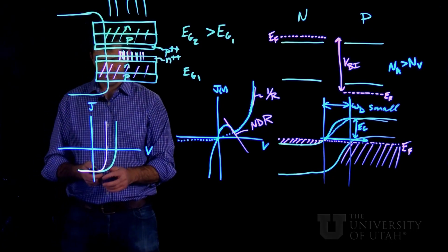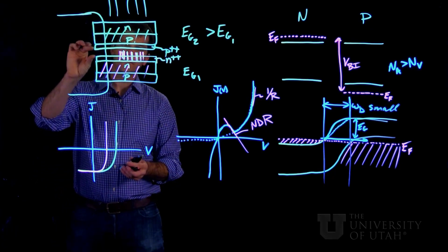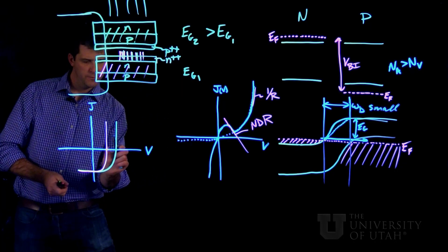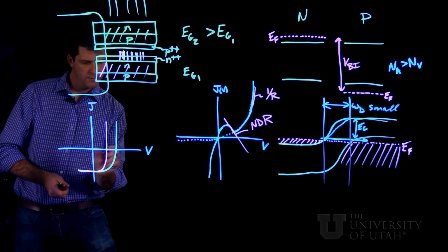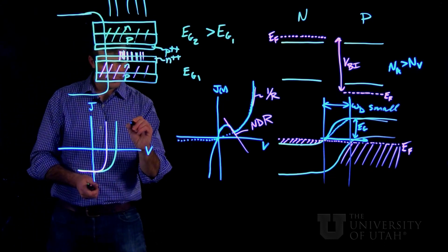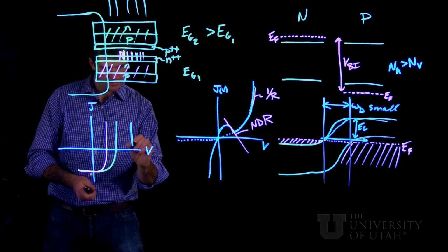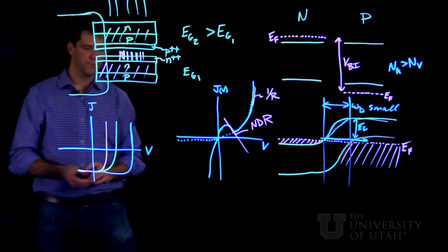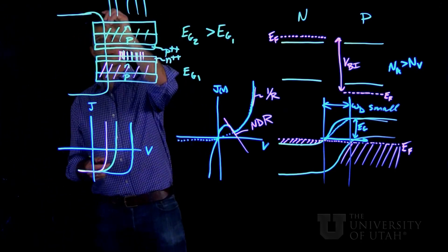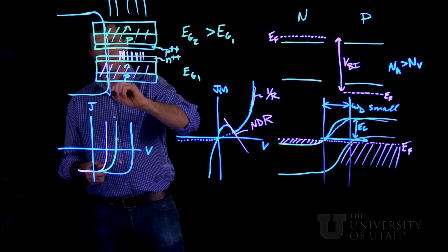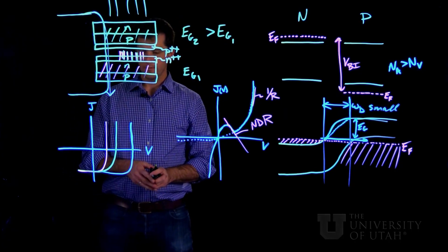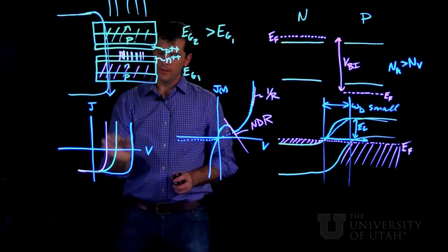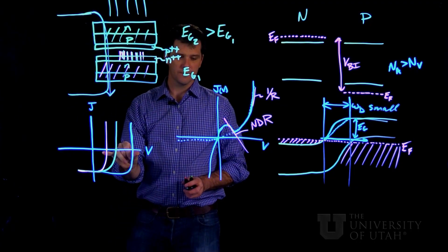and something like this for the red one. And if we have a nice tunnel junction between them, what it means is that we can add the voltages. So we take the red voltage here and we add it on, and our overall series connected tandem solar cell should have an IV curve that looks like this, the blue one, the total current and voltage going through the device. So if our resistance is very small in the tunnel junction, we get the addition of these voltages effectively.